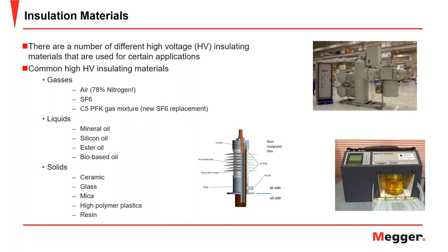And the takeaway from this is that each material has its own permittivity and dielectric strength, making some of these materials more susceptible to PD activity, as well as the different properties of these materials causing different characteristics of partial discharge themselves.